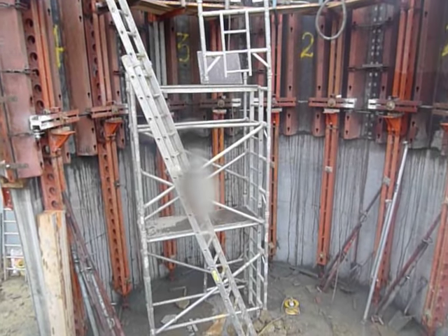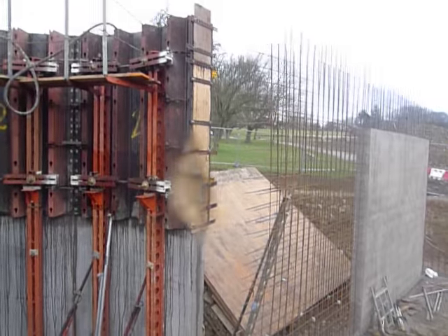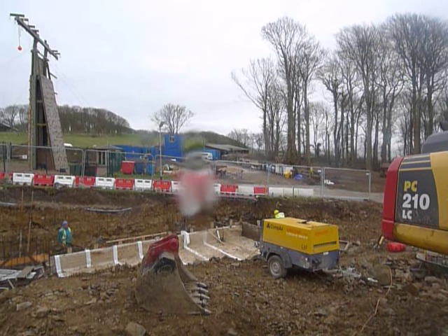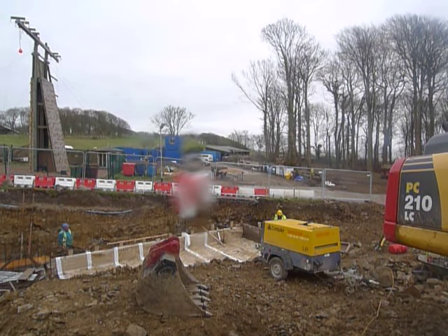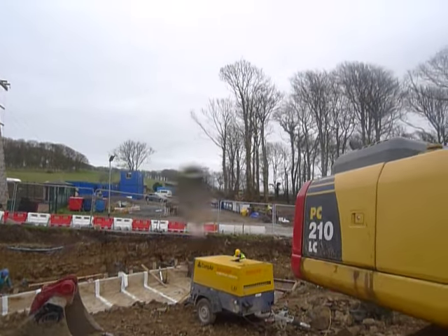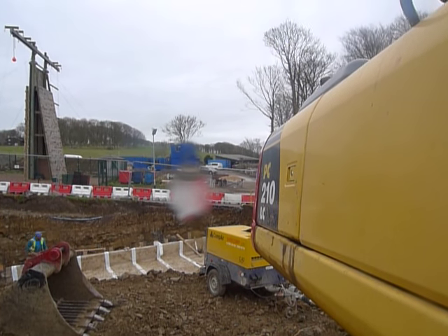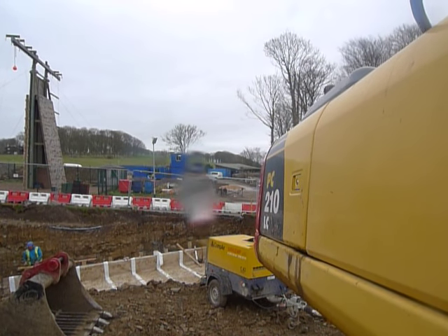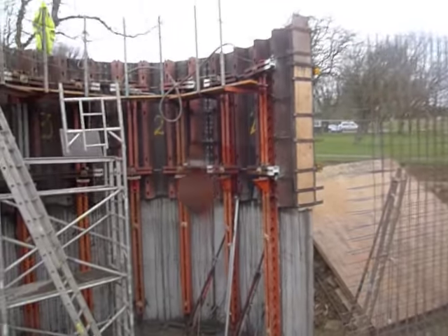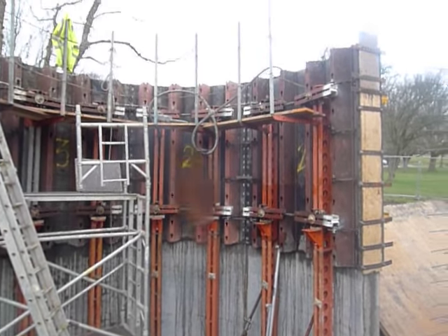Before, the shutters were, as you see, bent to a shape. Now for that shape, they use a former, and the former is on site. It's on a little table, and if you look across the site from where I'm standing, and go through the centre of that compressor and look in the distance, you'll see the former there, and the curves that the shutter gets placed on are bent and curved to that shape. Okay, so when the shutters come across, they're ready formed. They shouldn't ever be altered on site after that.